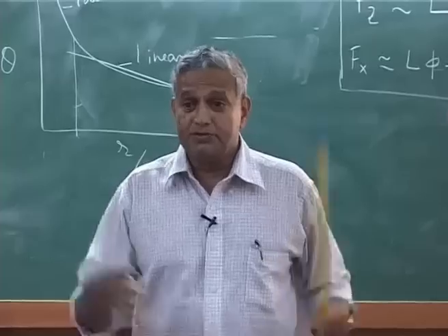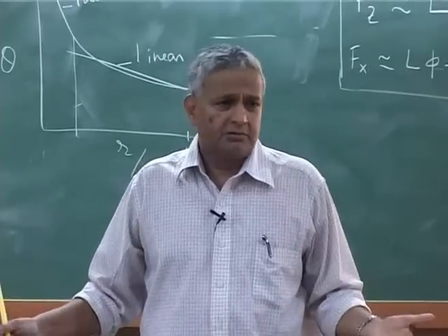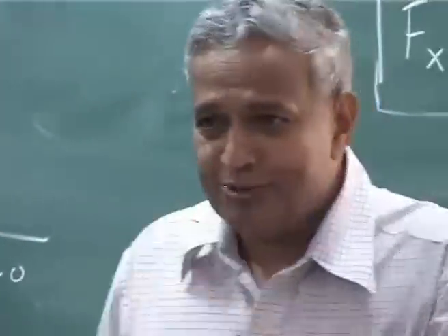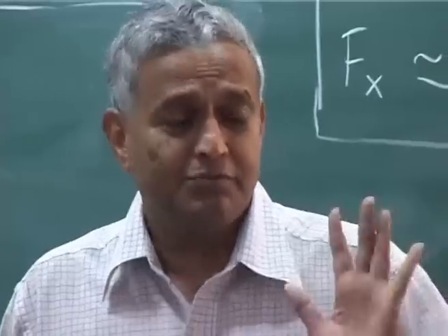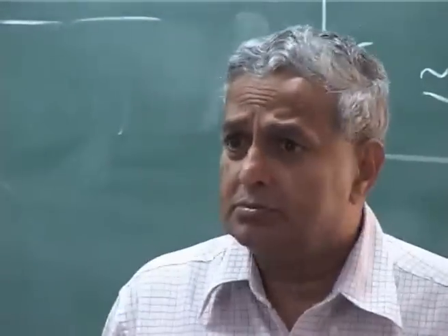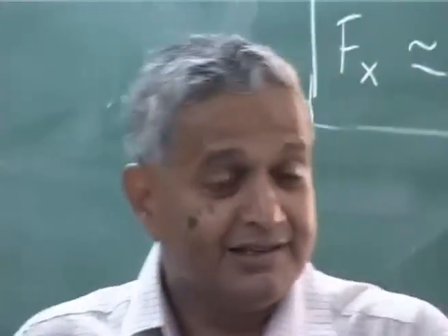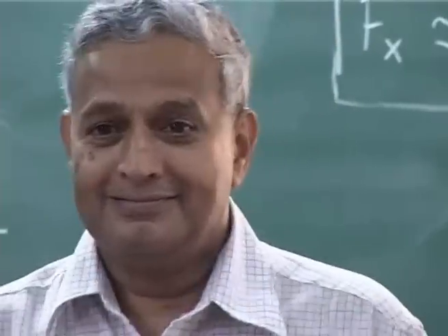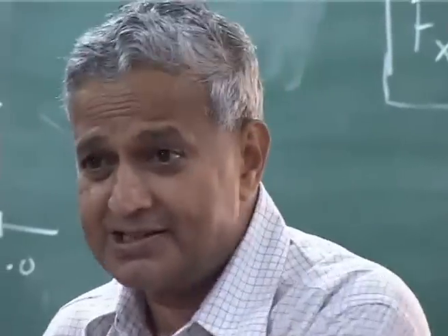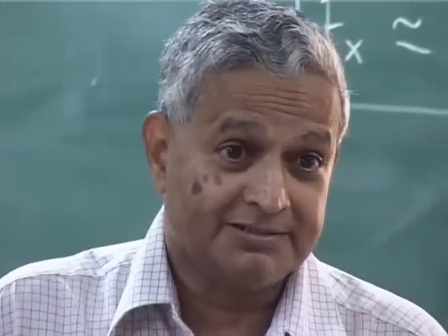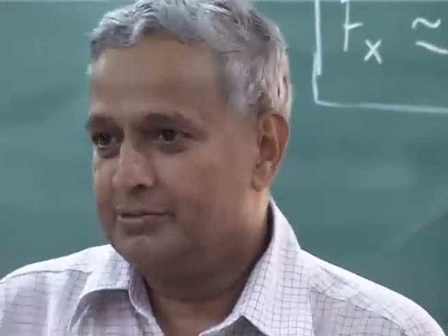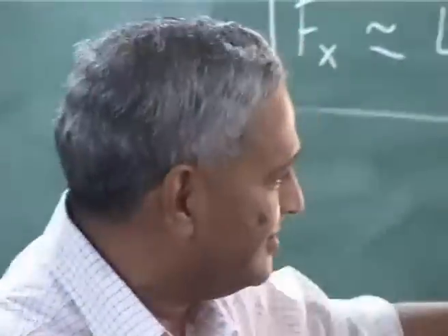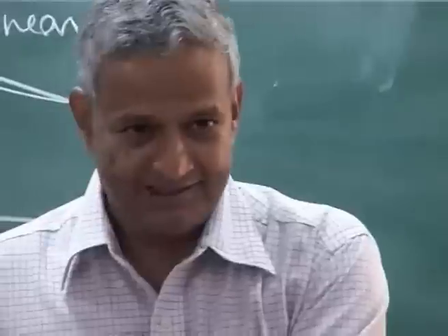Please understand, I assumed inflow is constant, but I do not know whether it is constant or not. That means I said lambda i equal to root of Ct over 2, I assumed it, but it is not true. That means even in this very simple expression, I am making an error. I assume this is constant, but I do not know whether it is really constant or not. Okay, this is a problem. You can use that, but you make errors. Now you say, how do I, later we will do, the torque part we will do in the next class. Okay.